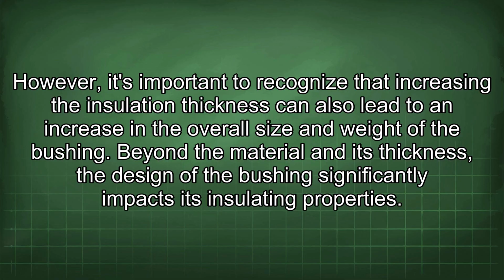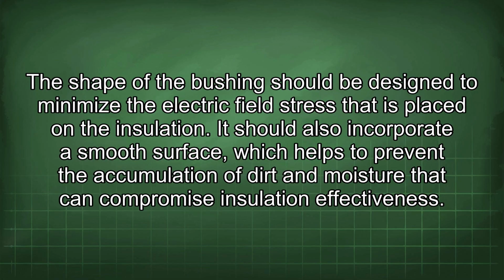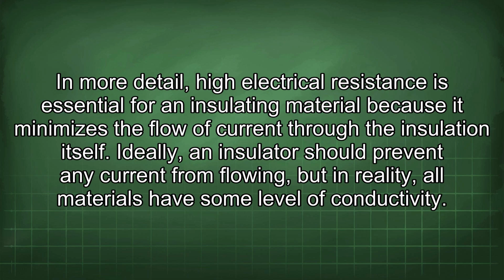Beyond the material and its thickness, the design of the bushing significantly impacts its insulating properties. The shape of the bushing should be designed to minimize the electric field stress that is placed on the insulation. It should also incorporate a smooth surface, which helps to prevent the accumulation of dirt and moisture that can compromise insulation effectiveness.